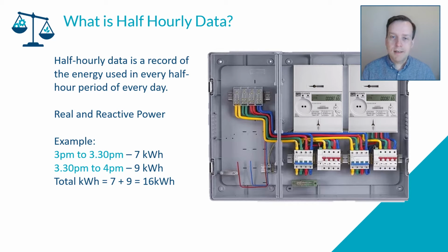So, the image on the right here, we have two half-hourly meters, and depending on the voltage level, certainly above 132 kV, depending on your metering point or your contractual billing point, you may have actually 2 meters, main and backup, and it's simply redundancy,